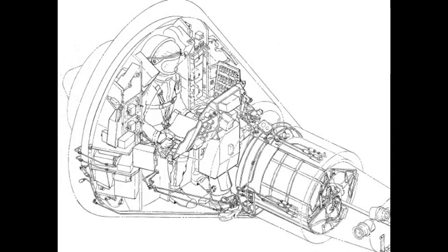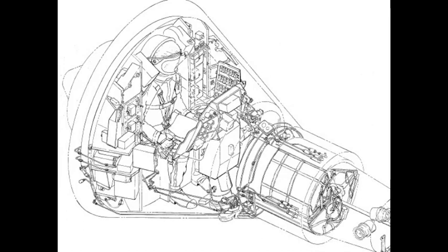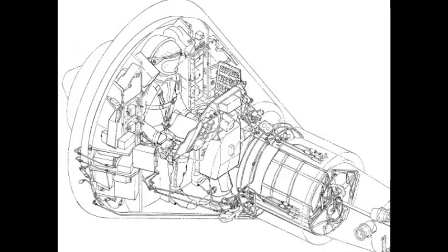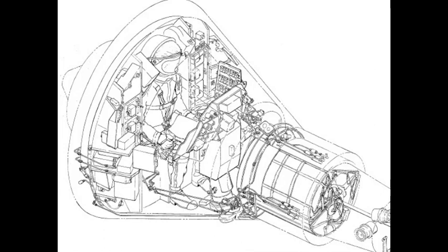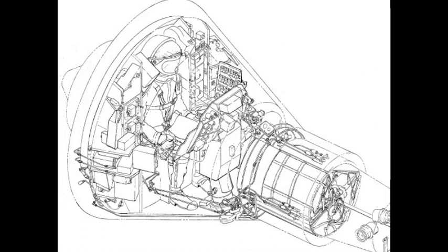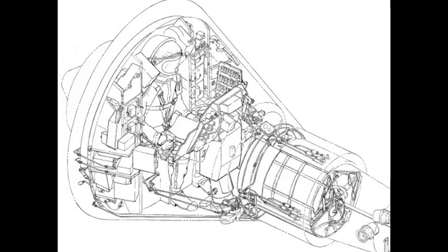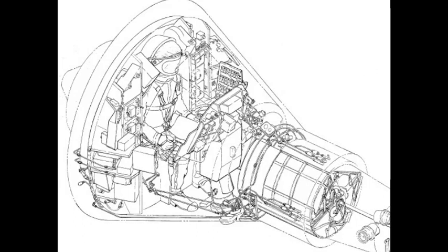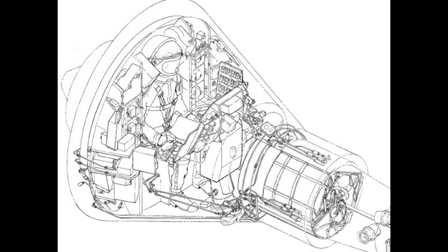A layer of thermoflex insulation is installed between the hat stringers and the external shingles to prevent excessive heating within the compartment. The cobalt shingles are individual panels bolted to the hat sections with allowances for thermal expansion. A set of 4 flotation bags, equally spaced around the outer periphery of recovery compartment, are located beneath the shingles. Flotation bags are provided to prevent possible submersion of capsule during astronauts' egress following capsule water landing.